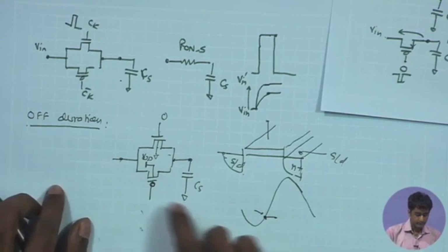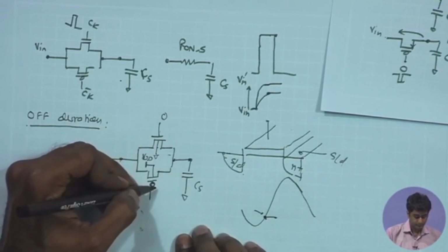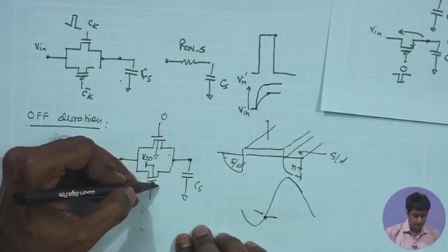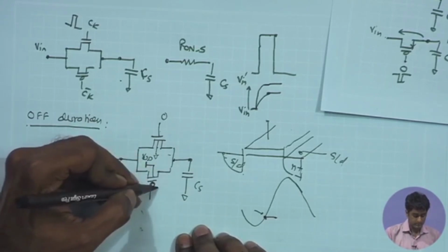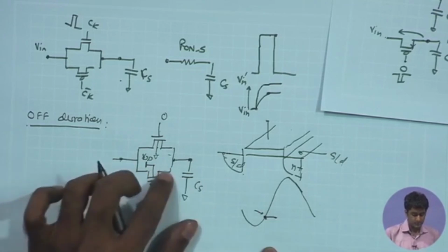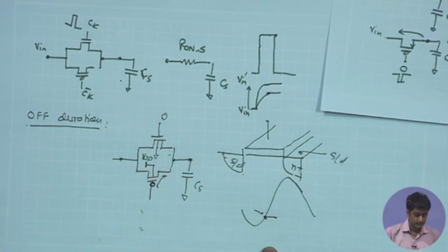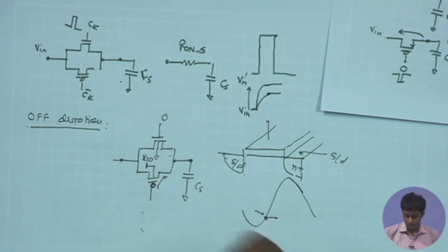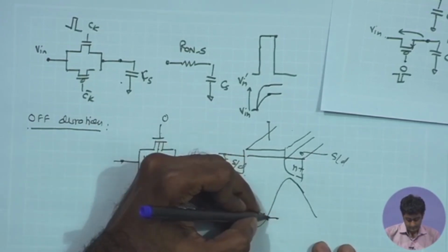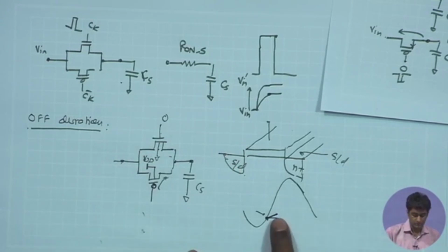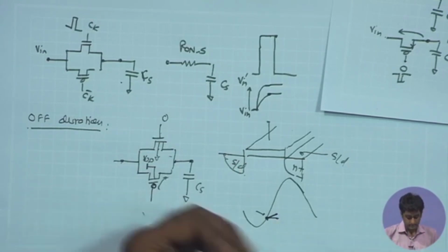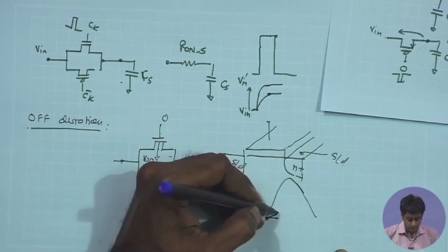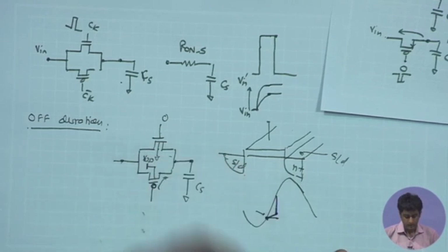You will have significant reverse bias current flowing from the substrate towards the source drain terminal of the PMOS over here. As a result, this can lead to increase in the overall sampled voltage, right. So, what we expect here is that you are going to get a slight increase in the sampled voltage, rather than being constant it will show some increase, and then next time when you are putting the switch on, again it will go towards the new value,